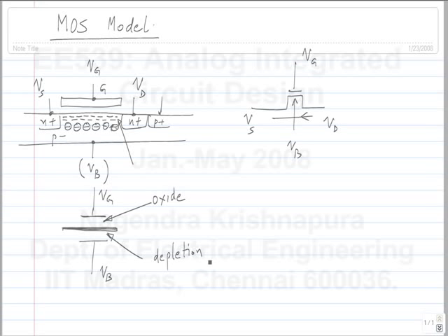Why is it tied to the lowest potential? So, the dangerous point is this: you don't want a forward bias junction between the drain and the substrate. Okay, and also typically, if you end up with one forward bias junction, if you have many junctions close together, you know about the possibility of CMOS latch up, right? So things can get forward biased and can get latched up in some particular state. So although you can increase VB, you can't increase it too much.